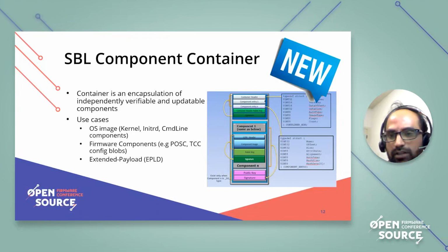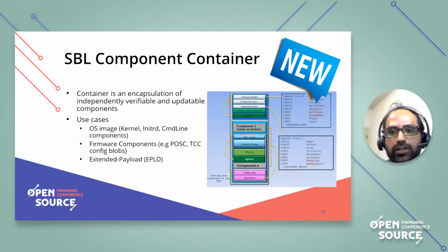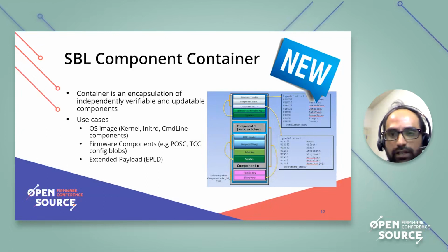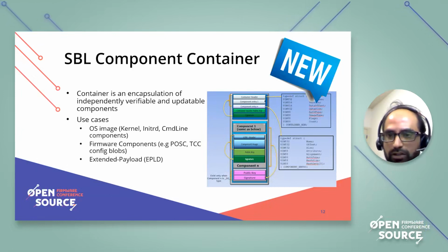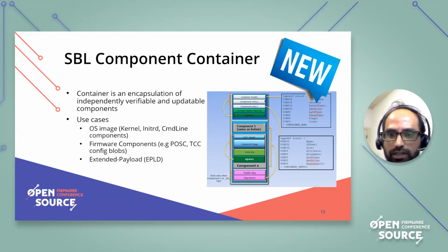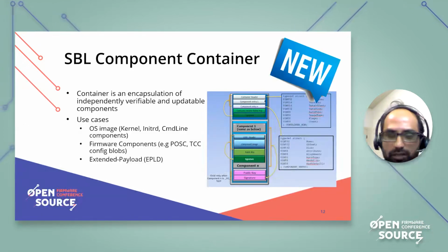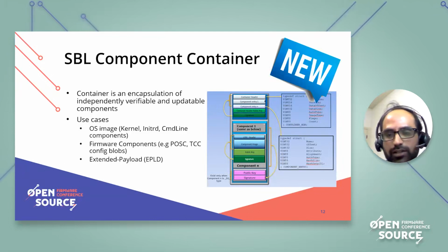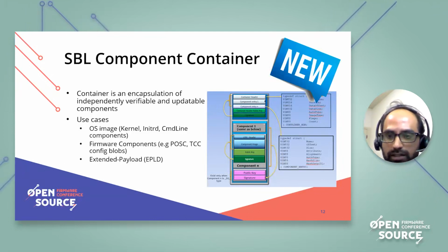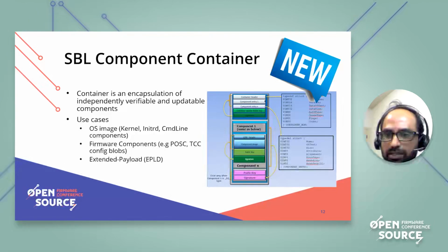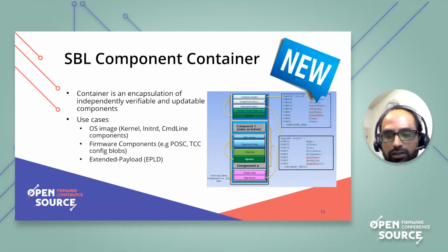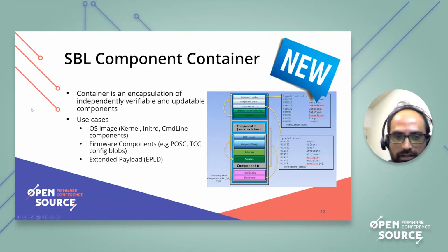And for the extended payload, we can provide the user with a choice to boot to what payload dynamically. If we can give them a list of payloads already in the boot flash, they can do this via a GPIO pin to select what kind of payload they want, or any other way. But since all the payloads are logically similar, they can be put as multiple components in the container and can be verified before launching each payload.